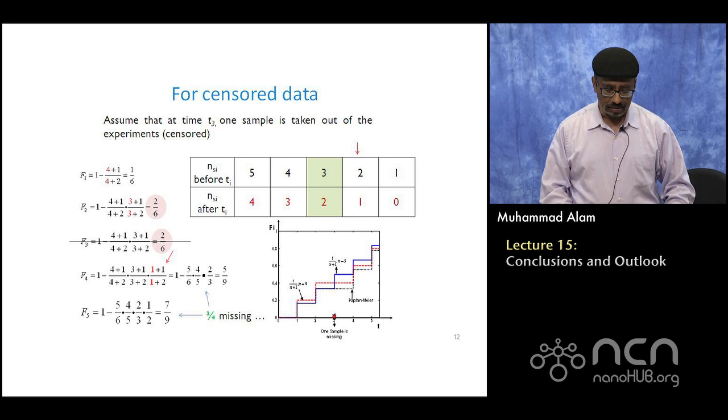But what happened was that over the weekend, one of the probes that was stressing the oxide accidentally got detached. Now, when you are trying to get the lifetime of those oxides, up to that point when the probe got detached, the oxide actually survived just fine. So it is trying to tell you that although it did not fail up to that time, and you're interested in failure time, by surviving up to the last point, how do you account for this information?